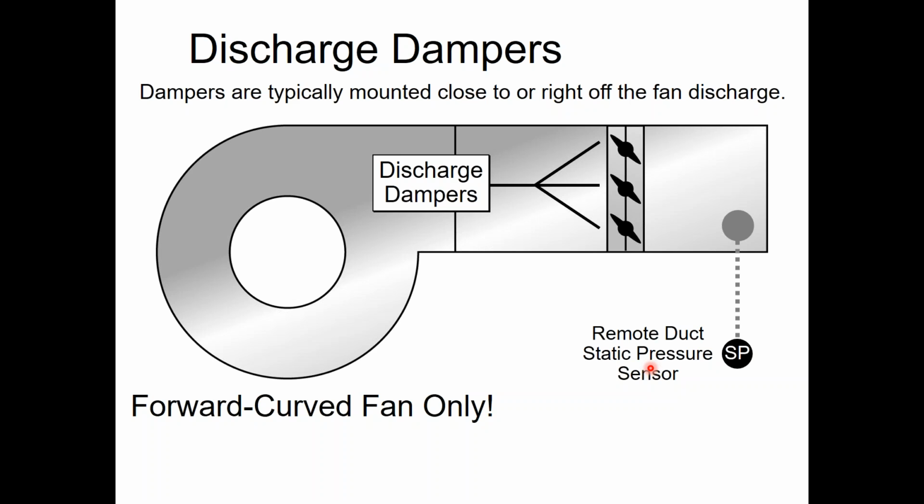You could have done discharge dampers. So instead of having dampers over here on the inlet of the fan, you could put a discharge damper on the outlet of the fan. I've never actually seen anybody do this, but I figured I'd throw the drawing in here.